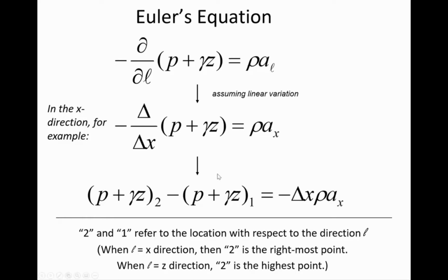So this Euler's equation takes 2 factors into account. It takes the effect of the external acceleration, and this, by the way, is local acceleration, that causes the pressure change that is quantified by Euler's equation. This local acceleration, meaning acceleration with respect to time, causes a variation in either the pressure or the water surface, depending on whether the tank is capped and whether the water is able to slosh, whether its elevation is able to change.